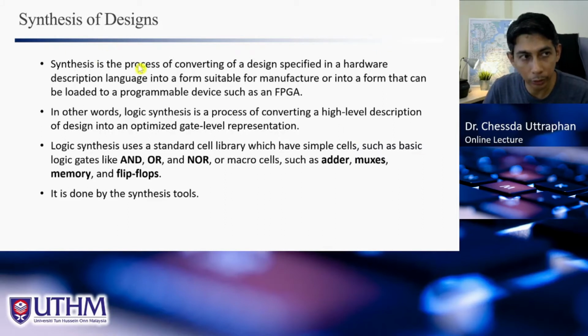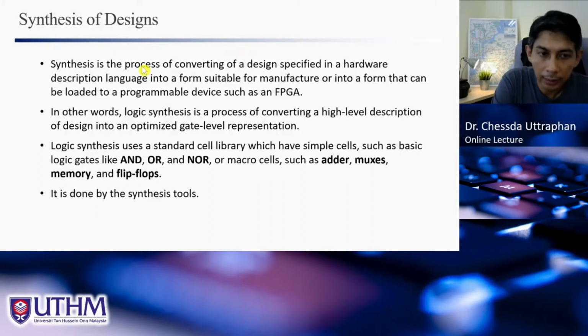And now we go to synthesis of design. Synthesis of design means we translate from the code to the circuit, to the schematic. This is actually done by the software. The Verilog compiler will do the synthesis task for us. We as a designer, we write the code and let the computer synthesize the code to produce the circuit for us. But we as a designer need to learn this.